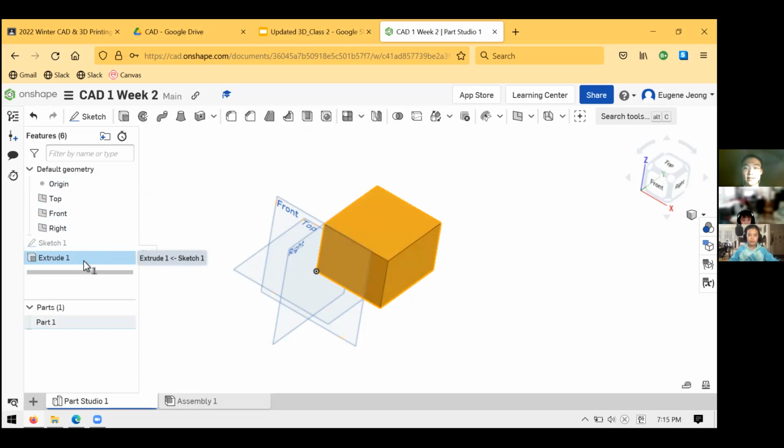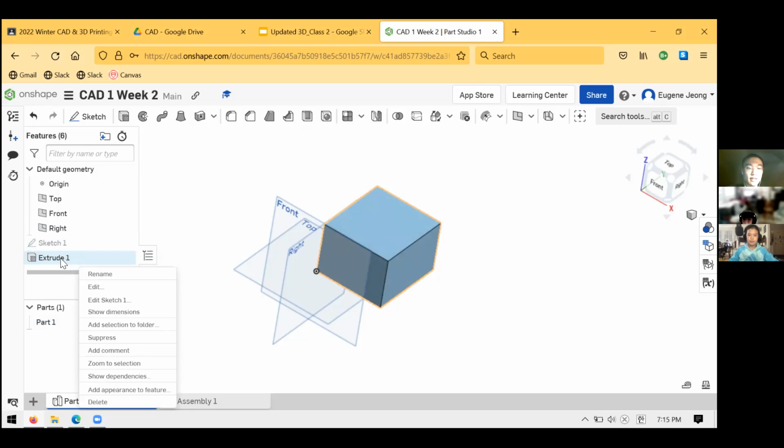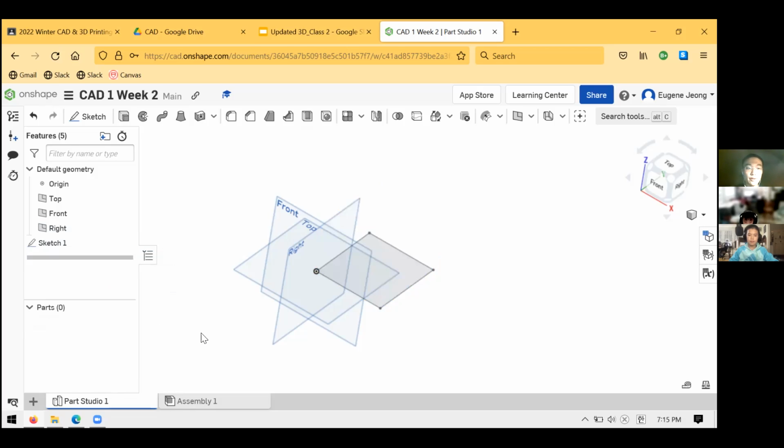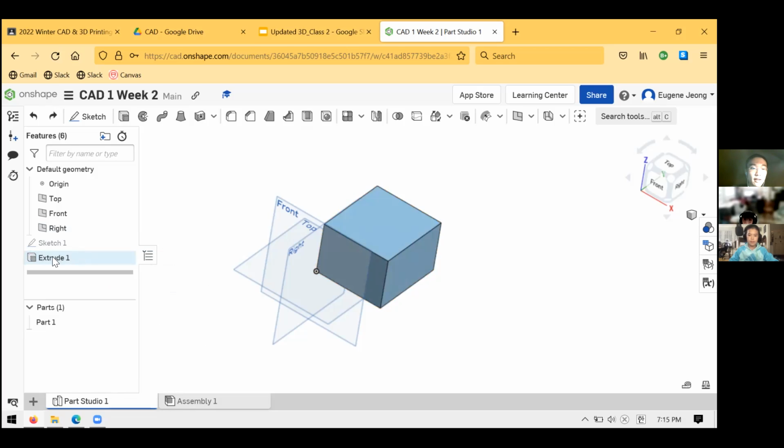My reason is I'm going to take a step back and go back to the sketches. So I'm going to delete the extrusion. And the way I can do that is just go to my feature tree. I can right click it, just like I would to delete a sketch entity, as you saw, and I can just hit delete. Another thing I can do, I undid it, is I can just left click it and hit delete on my keyboard.